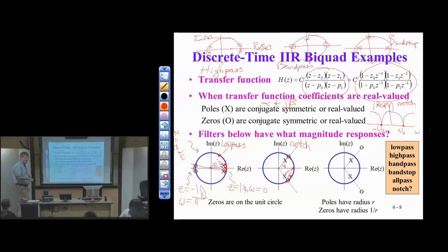But we can get rid of the interference on a subsequent stage of processing, which is to notch it out. And we do this in practice. So for noise and interference that's outside of a band of frequencies we care about, we apply the appropriate bandpass filter or low-pass filter, whatever it happens to be. And to get rid of interferers that are periodic inside our transmission band or band of interest, then we can do a notch filter.